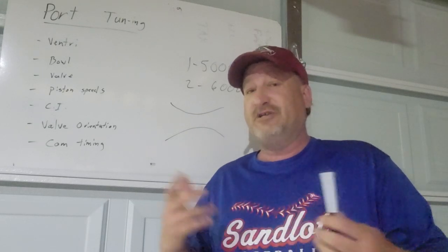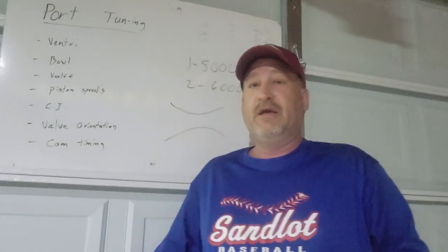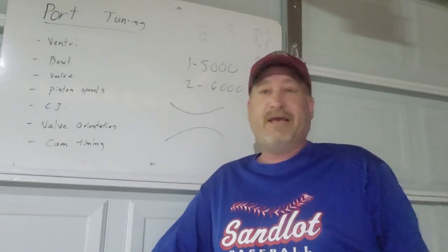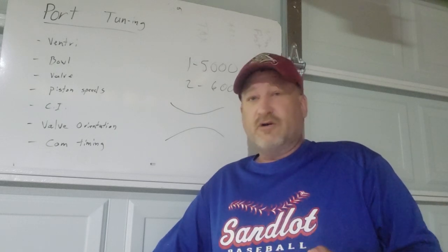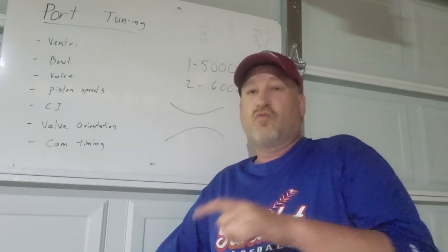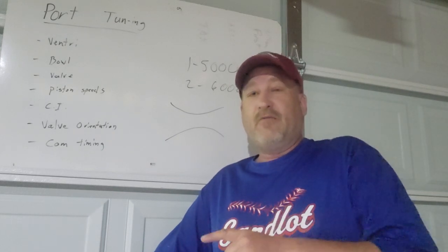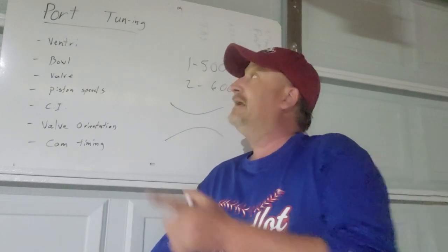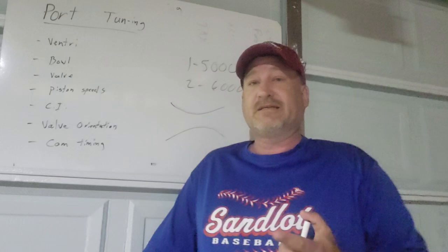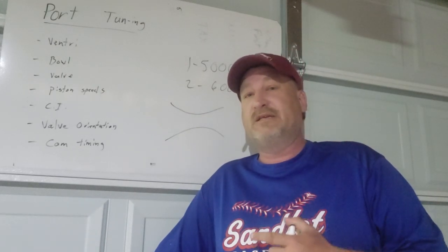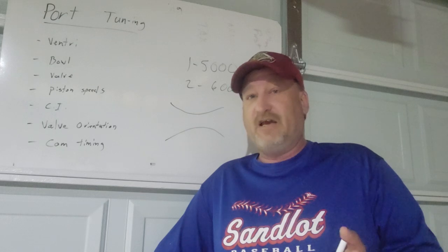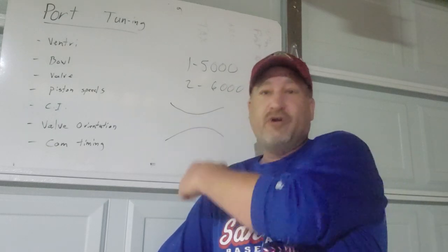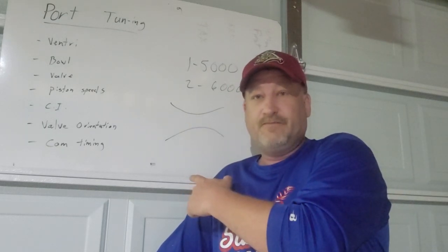And Chevy's engineers, even Smokey Yunick, played around with different connecting rod lengths to alter the rod to stroke ratio. Now that rod to stroke ratio plays into the port tuning, because that is when it is going to be exposing the vacuum and how aggressive that vacuum is transferred onto the intake port.